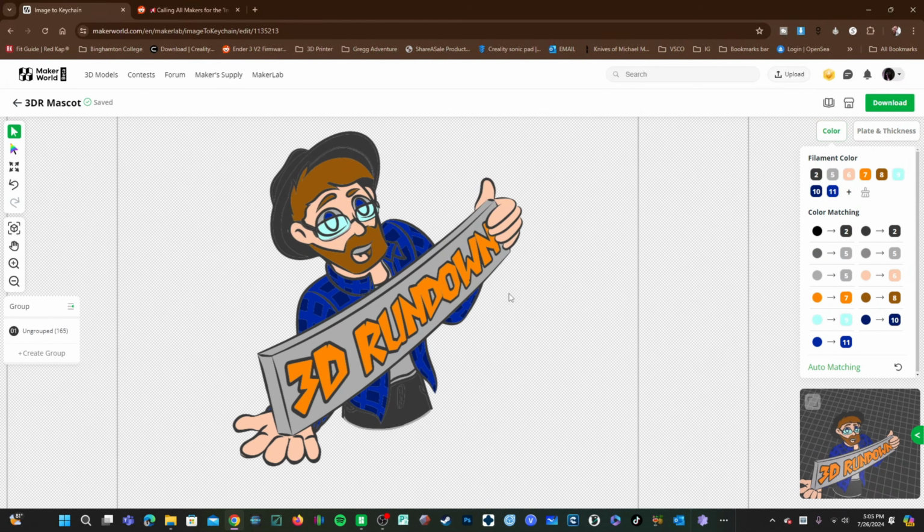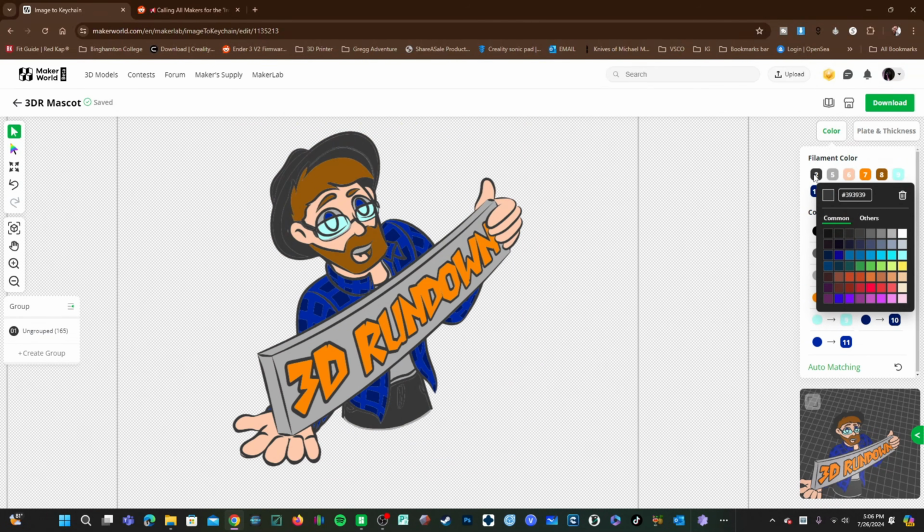Here you can assign different colors. For example, I'm not thrilled with how the blacks look. I'm going to go ahead and click on that color, which is color number 2. By hovering over color number 2 over here, you will see all of the areas designated with that color highlighted in yellow. It's quite a bit. I will click on it and assign a darker color black.